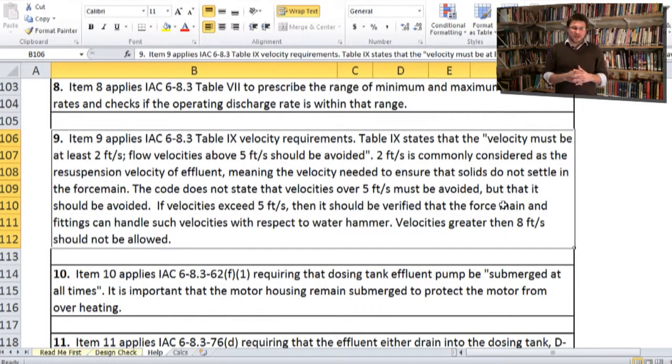If you have a highly pressurized pipe and then you instantly shut off flow to it, it creates what's called water hammer throughout the pipe, where it shakes. We see it shaking, but really what it's doing is sending lots of pressure surges through the pipe. And those pressure surges can actually burst the pipe. And so when you have high velocities and they shut off real quick and high pressures, then you need to make sure that your pipe doesn't explode from water hammer.